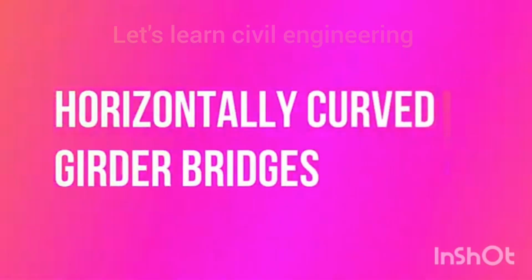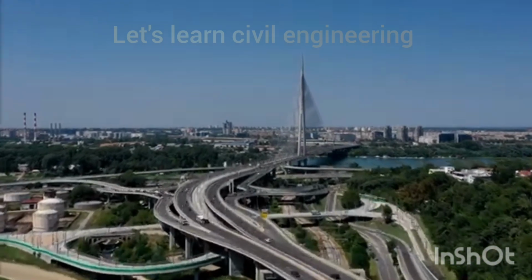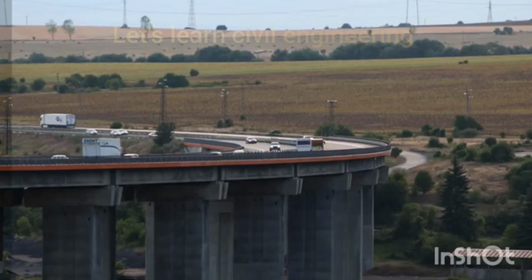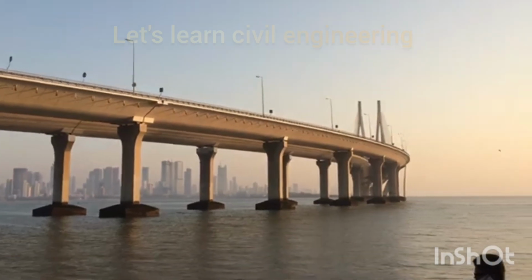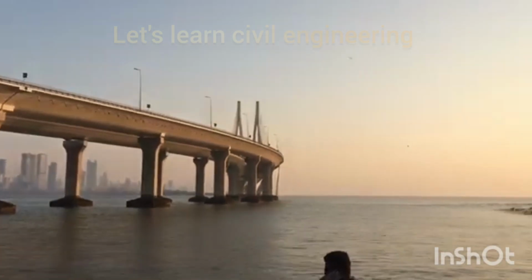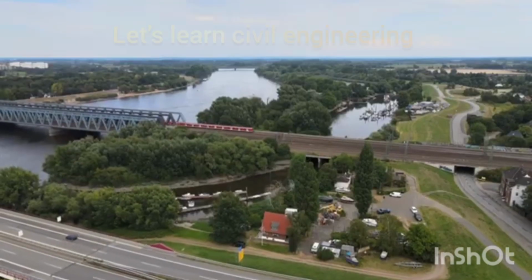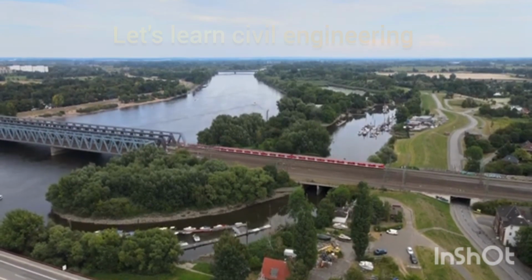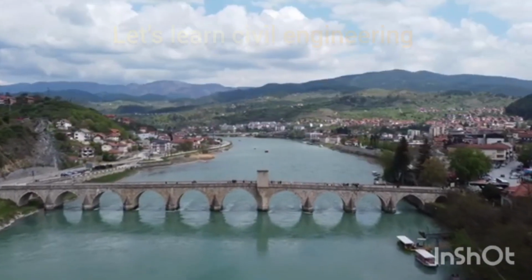Horizontally curved girder bridges. Horizontally curved bridges are constructed where complicated geometrics, limited right-of-way, and traffic mitigation are involved. The superstructures of curved highway bridges are usually steel I-girders, steel box girders, or concrete box girders. Highway truss girder bridges. Few truss girder bridges are used as highway bridges today, although they are still used for railroad bridges.